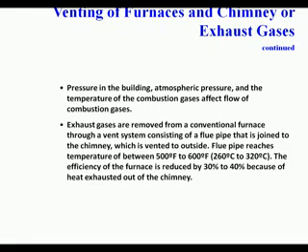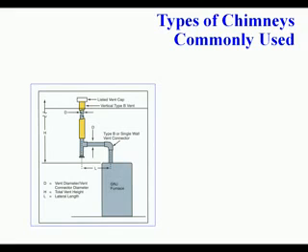There's a loss of about 4 to 15% through the chimney. The chimney or vent pipe should extend at least 2 feet above the highest part of the roof to prevent back pressures in the chimney or vent pipe under windy conditions. The combustion gas flow is affected by the pressure difference between combustion air entering the furnace and the combustion air leaving the flue or chimney. Pressures in the building, atmospheric pressure, and the temperature of combustion gases also affect the flow of combustion.